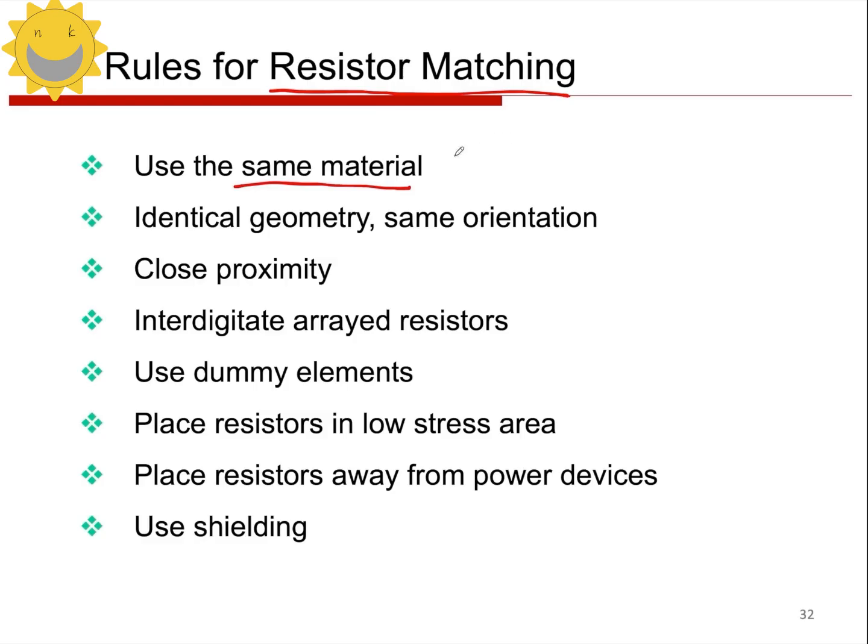Why is that? Because, as we mentioned before, when implementing resistor devices in integrated circuits, we can use many different types of resistors, right? For example, there are polysilicon resistors. What else is there? There's also the injection, right? The N-type or P-type doping injection, and this kind of injected resistor. What else? The N-well, right? The N-well can also serve as a resistor. So, we have the injected resistors and N-well resistors, etc. As you can see, there are quite a few types of resistors.